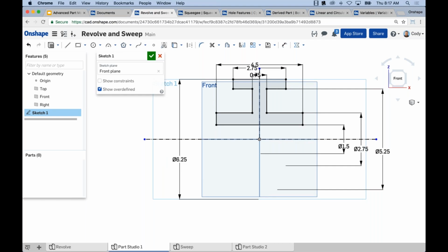Okay, so a big tip, and this is particularly important in Revolve sketches like this, if you dimension relative to a construction line like this, if you move past it, it will automatically double the value and add that diameter symbol, implying that this is a diameter dimension. So a big one, if you're constructing a lot of Revolve profiles, you'll probably want to dimension that way. As I said, not all scenarios, but most you'd want to dimension in diameter.